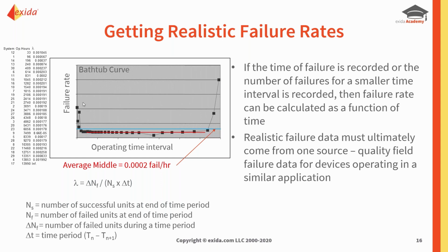So at this point, this is known as infant mortality, and what most manufacturers will do is some form of stress testing to be able to wheedle out weaker components before they get into circulation, because they don't want warranty returns, of course. And then what happens here at the back end is what I was talking about earlier with the wear out, where the normal stresses and strains start to overcome the strength of the device or equipment.